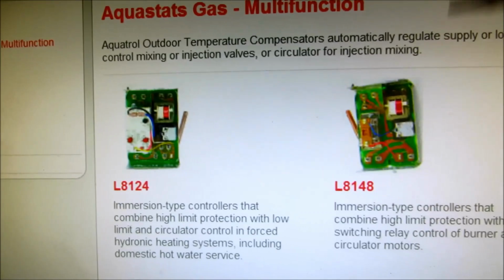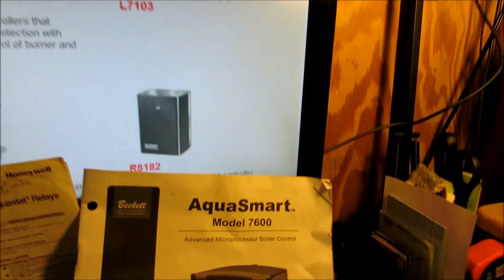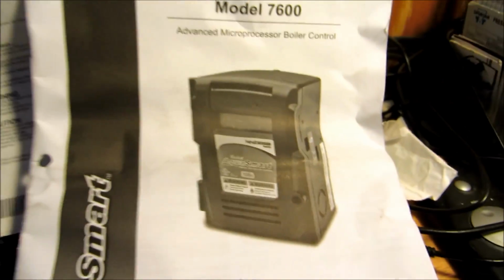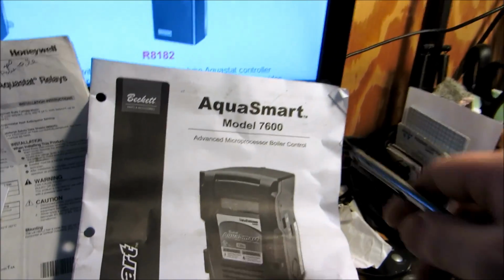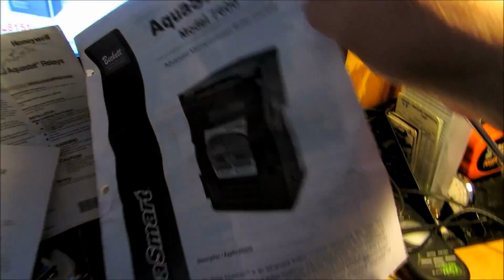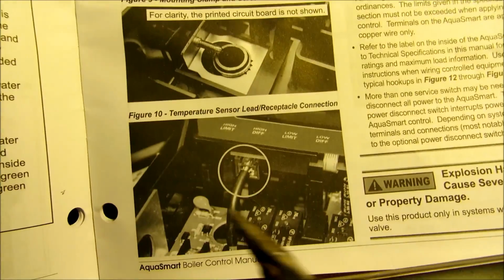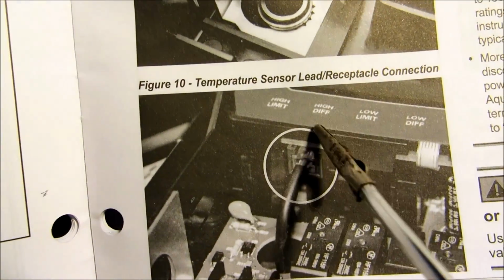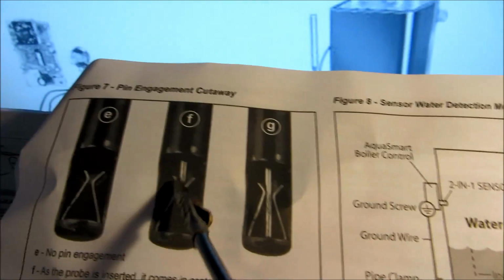That's a good control. Now I'm going to go over some other controls. There are some other controls they've got out now, these smart controls, Aqua Smarts, on the gas and the oil. Again, oil would just be 110, gas would be 24 volts. These have a little probe in there that you have to make sure is in all the way. This one almost looks like a phone plug, like you'd plug a phone in. Then there's a little flexible cable that you have to make sure is inside the well all the way. I've had a lot of problems with these if they're not pushed in all the way.